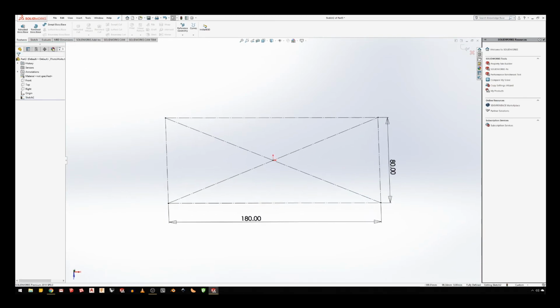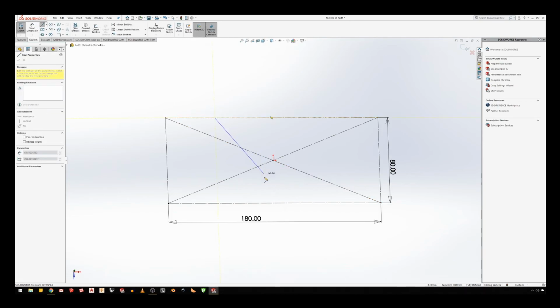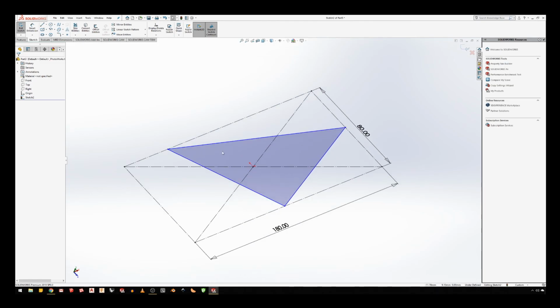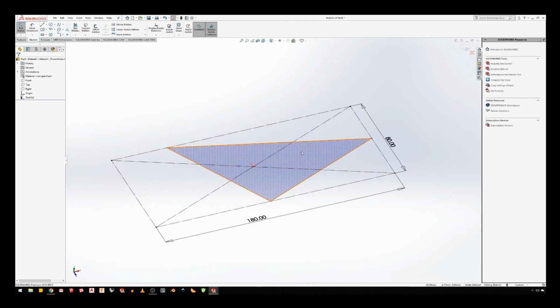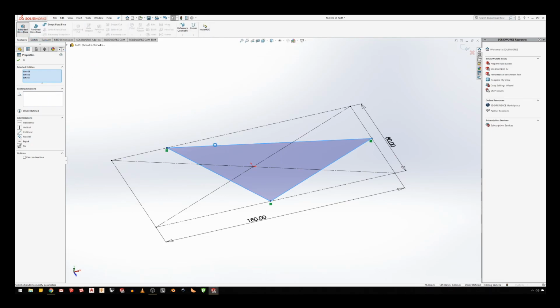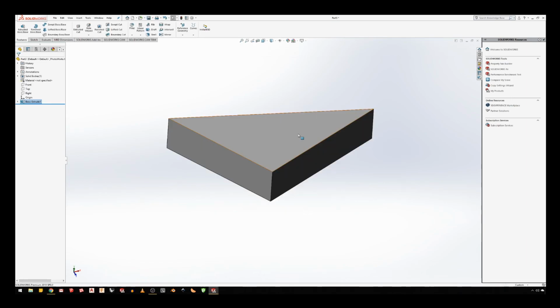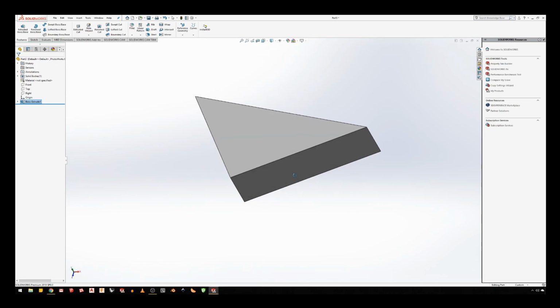So then we could start sketching within that by using, let's say, the line tool, and we could start doing some kind of random sketch that's contained. And as you can see, it's recognized that enclosed volume, but not the construction line. So if I were to turn this into an extruded object now, thusly, hit enter, all my construction stuff disappears because basically it was ignored.